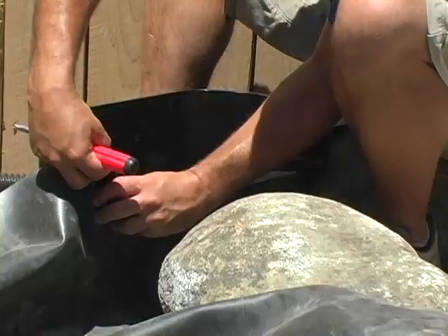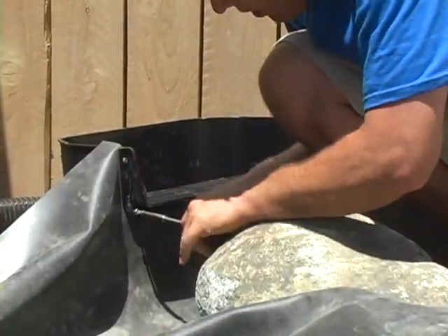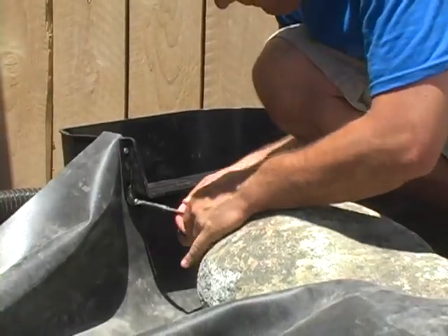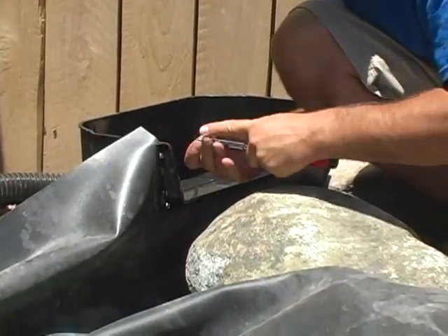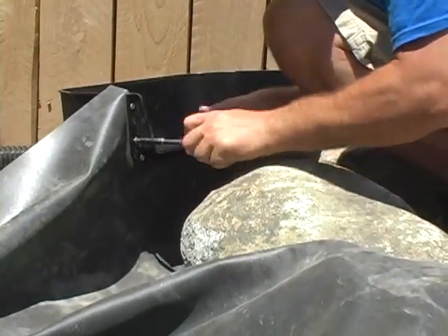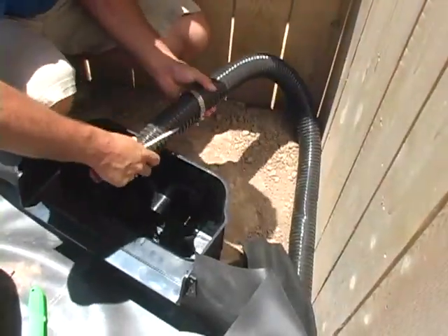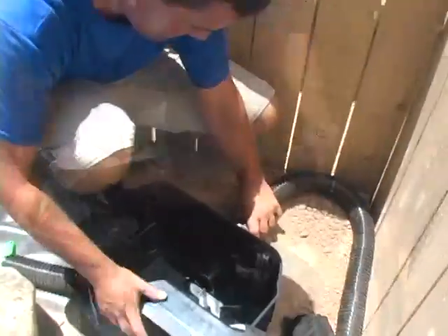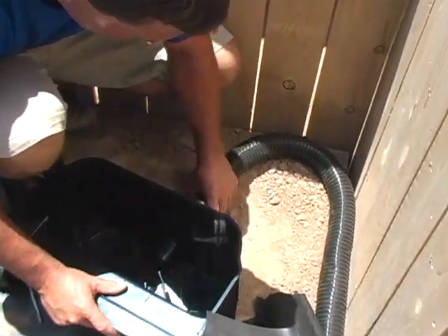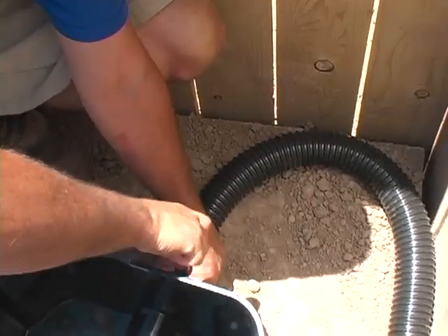Now you can secure the liner to the filter weir with a liner bracket by installing 4 screws into each corner. Then install the remaining screws, tightening each evenly by hand until they are flush with the faceplate. Trim the kink-free hose to length and connect it to the back of the filter weir. Use a hose clamp and screwdriver to secure.